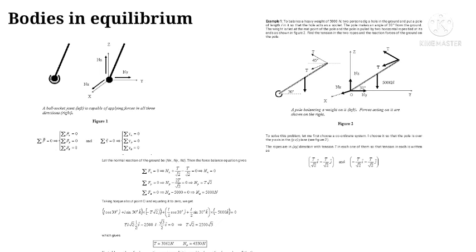Consider a ball socket joint, in which a ball is supported in a socket, as you see in figure 1. A ball socket joint provides reaction forces Nx, Ny and Nz in all three directions, but cannot apply any torque. This is a little hint from 2D. Let me solve an example using such joints.